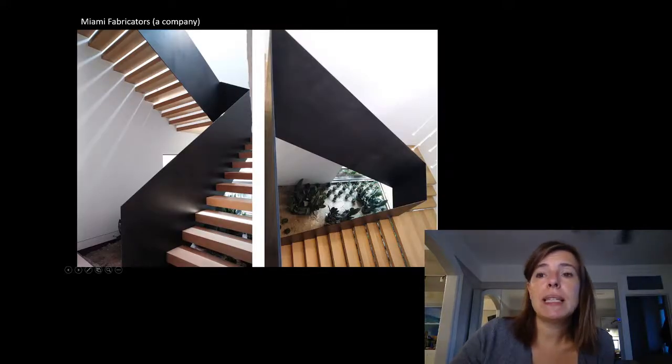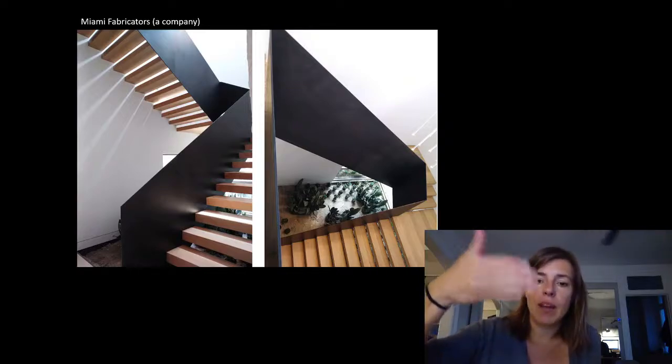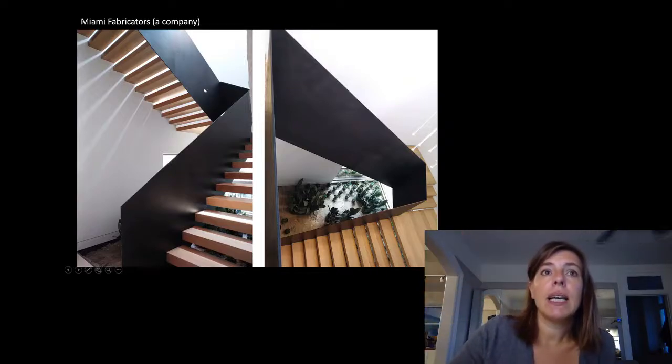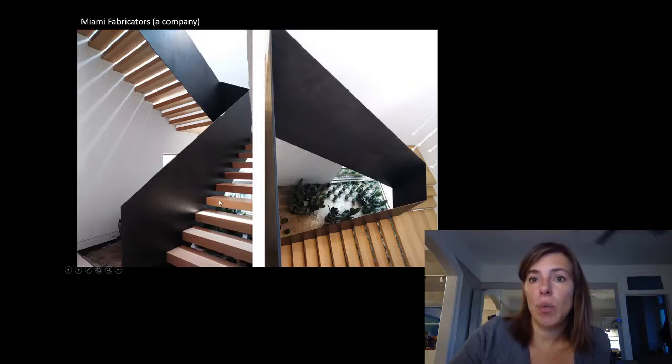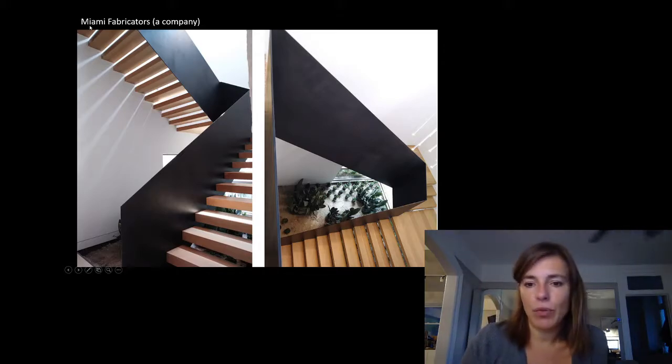A steel plate stair, where there is some connector. So this most likely had something welded to it that connected to steel here. So it was connected in the shop where they were able to grind down and smooth out whatever the connector was, because when you weld plate steel, you can cause kind of a visual damage on the outside. So they would have done that in the shop and then had the connector be in here that they did on site, so that they weren't welding this on site and then having that chance of an image on the outside. This was some Miami fabricator. I couldn't find who they were.